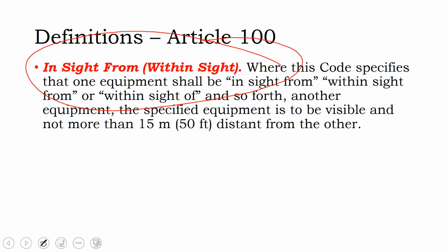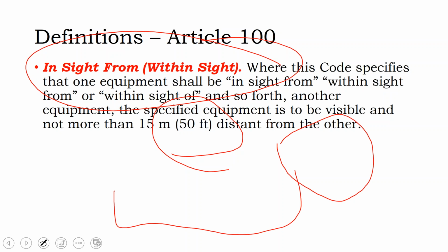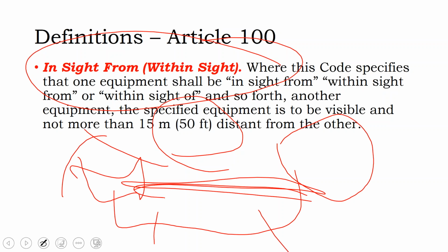And I had an issue where I had a solar array that was about 50 feet from the home. And so we didn't need to have a disconnect switch out at the solar array. We have a solar array, an underground wire run, and then our house. It's less than 50 feet between the house and the solar array. And the question is, well, do you need a disconnect switch at the solar array? No. It's only if it's greater than 50 feet.